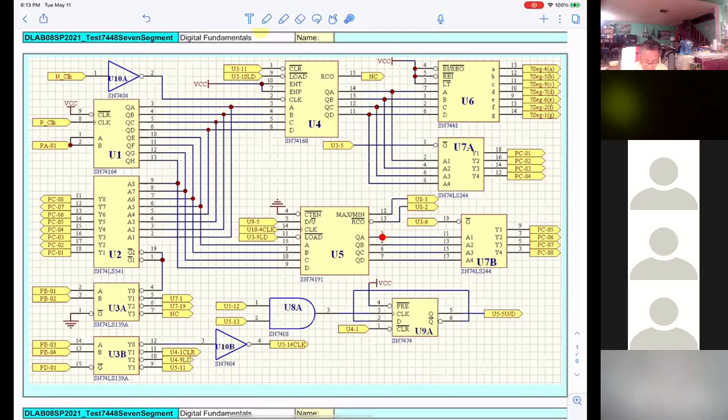Now, what you need to do, pin 3 comes out from A. You go take a measurement at pin 15. If pin 15 is 1 and pin 3 is not 1, then maybe the load here, you have to take pin 11. It must be 0. Okay? If you get a 0 on 11, you get pin 15 at 1 and do not get pin 3 at 1.